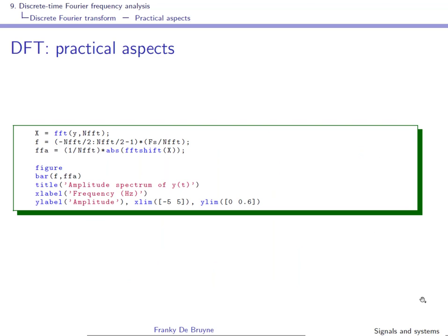We can now compute the DFT, and to compute the DFT we'll use the command FFT. We'll see later in the course that the FFT is an efficient algorithm to implement the DFT. Right, so what will come out over here is a vector Fn as defined previously. It's always a good idea to remember what this means.